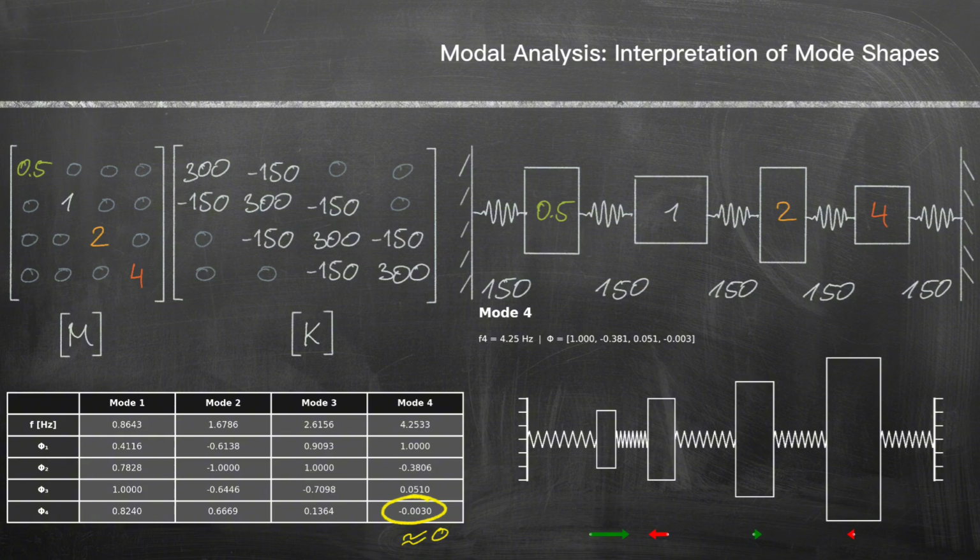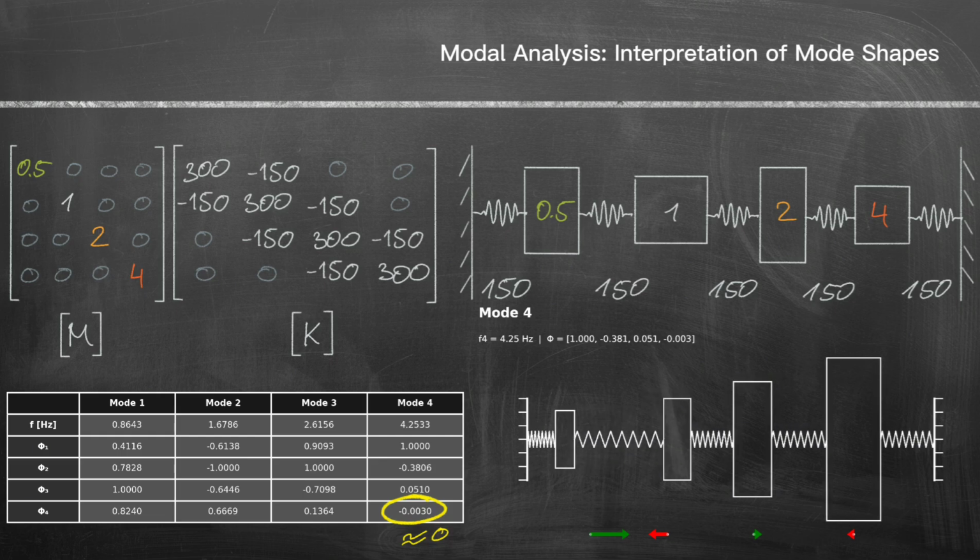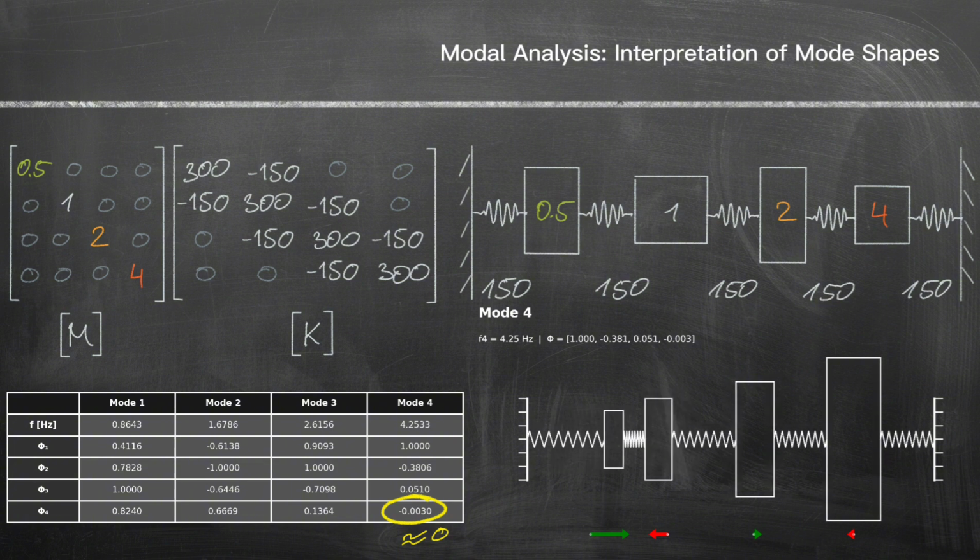From a practical standpoint, this has direct consequences. Exciting the system at the nodal point of a mode will hardly activate that mode. Likewise, placing a sensor at the nodal position provides little information about that mode.